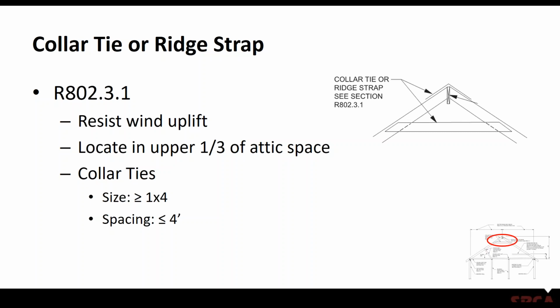Today, unfortunately, you'd be really hard pressed to find a 1x4 that is actually graded for structure. The vast majority of 1x4s that are produced today are graded under architectural rules. The wood is still there, but unfortunately, it's very difficult because of the way it's graded. You can't put design properties on that material.